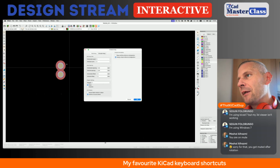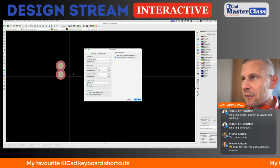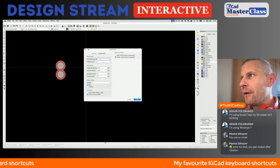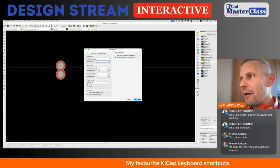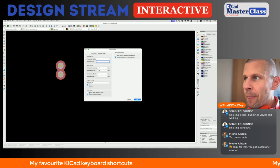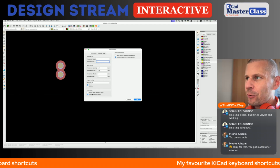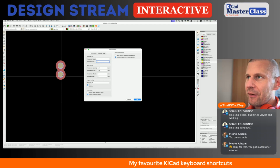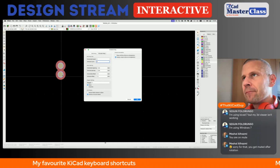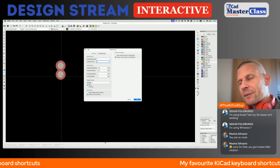And let's say you want to create an array 3 times 3 of this, not one via, but two strangely close together vias. So 3 by 3. What's most important thing, you had to set grid position here. I don't know why, but the default position is that this will stay in the center, and the 3 times 3 will be in the center of the group.